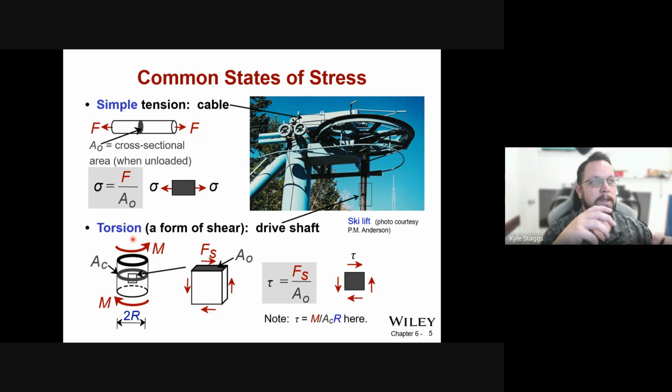The moment is the same units as a torque, and that's really the best way to think about this. If you grab onto the end of a wrench or a lever and pull it, you are applying a moment to that lever, and there is therefore a counteracting moment on the other end of the thing that you're rotating, whether it's a switch or something more extreme, like a winch on the front of a truck or the back of a tow truck.